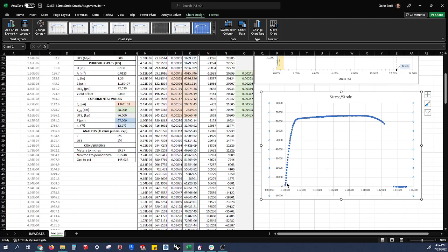Here we're cranking away, and you've learned something about why we're getting this particular shape. There's an ultimate tensile strength somewhere around here, where it's the strongest it's going to get, taking the most stress the material can. Then it drops off quickly and breaks here. We kept cranking and quickly got to zero force being applied.